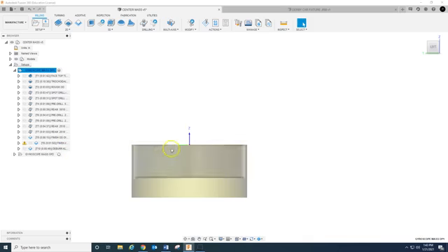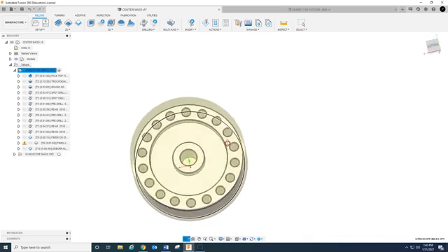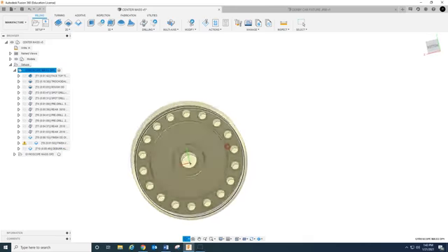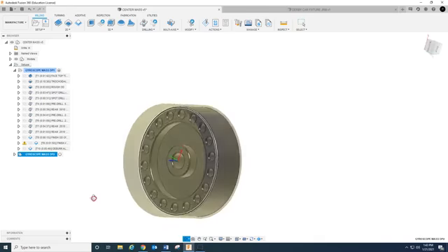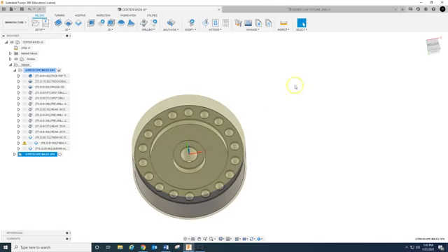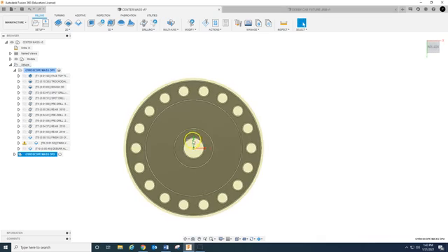Now, the reason for that is when we flip this baby over, when we put this thing on op 2, let's see here, flip that baby around. All right, obviously we're going to be able to pick up our part origin off of this hole. We'll be able to use a coax indicator and we'll be able to sweep this in really, really close.